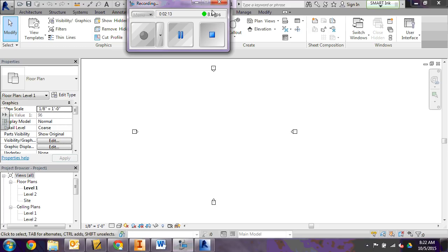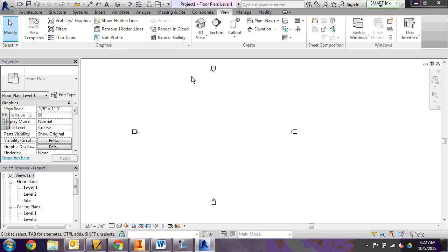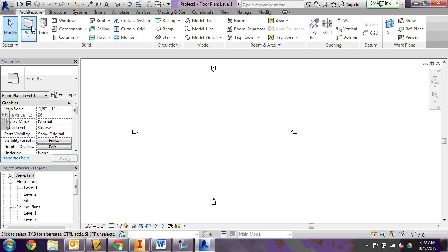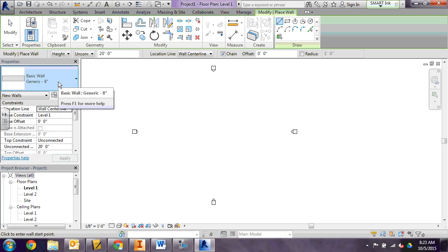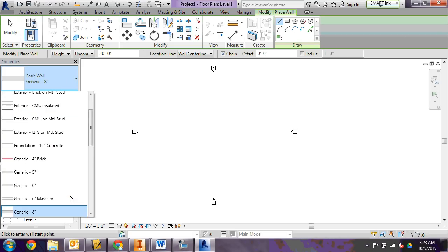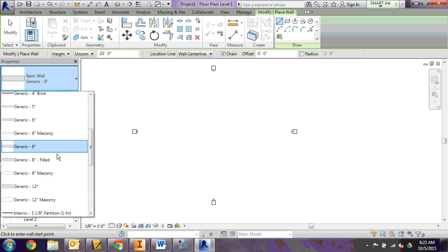All right, next you're going to start building your wall. It says build your classroom wall. You're going to select wall from the architectural tab. So up here are the tabs and here's architectural. And since we're building walls, we're going to click wall. If you hover over and push your down arrow, you can see there's lots of different walls that you can choose from to load.